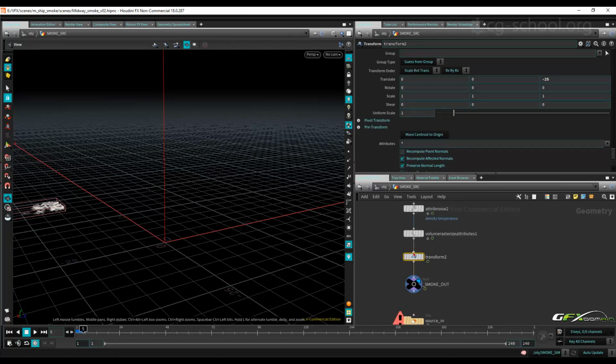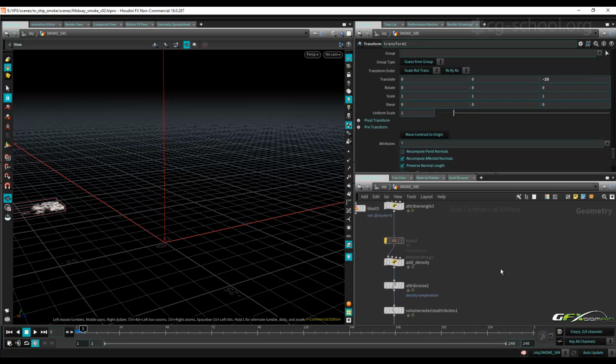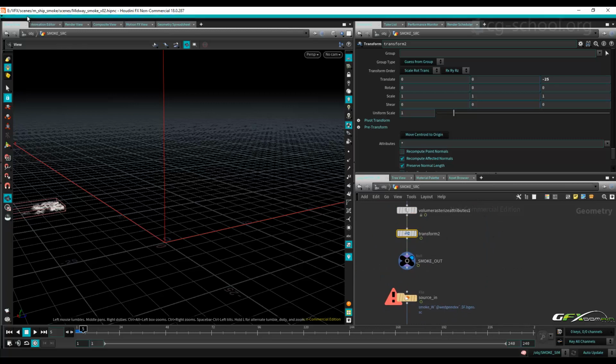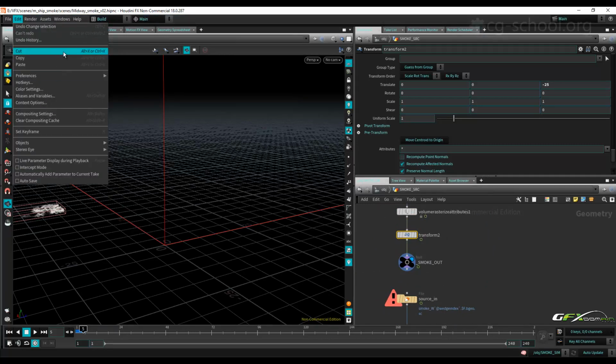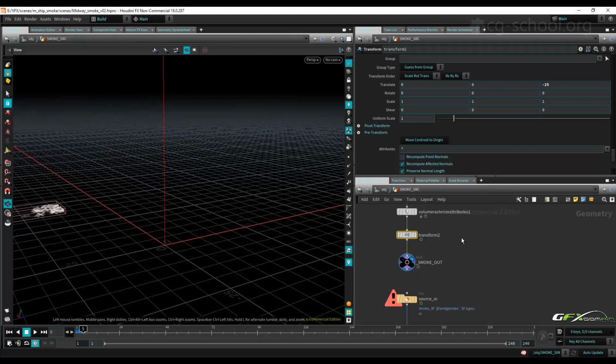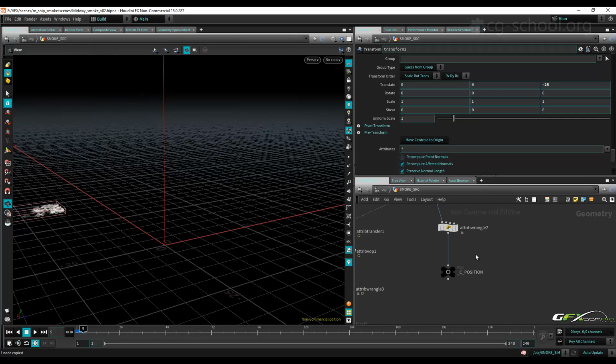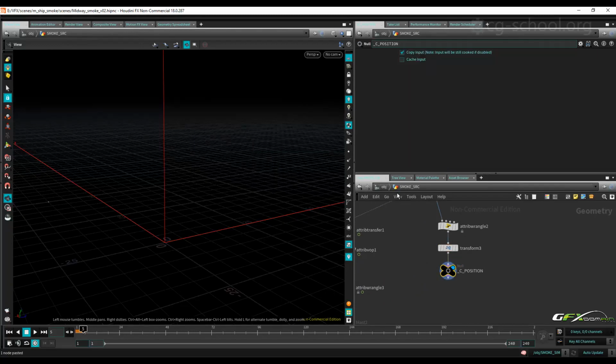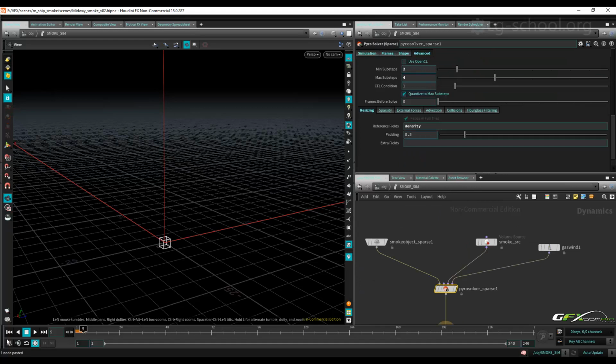That's my mistake. I transformed my source at 25 meters on this axis, and I should transform my points at the same position. So what I can do, I can create a clone, or we can create just a copy. So let me paste adjusting stuff here and transform those points at the correct position. Get back to my smoke sim, and yeah, now it's looking good. Now we have smoke. Let's just render or simulate a few frames.